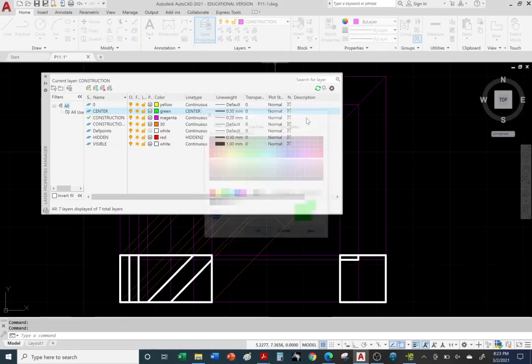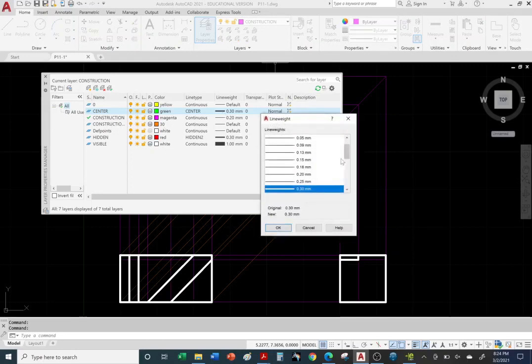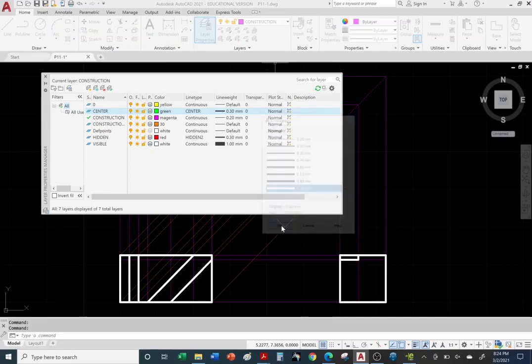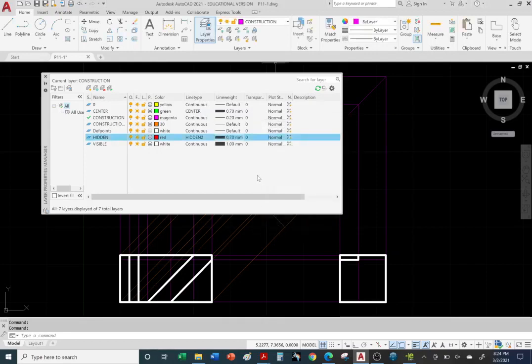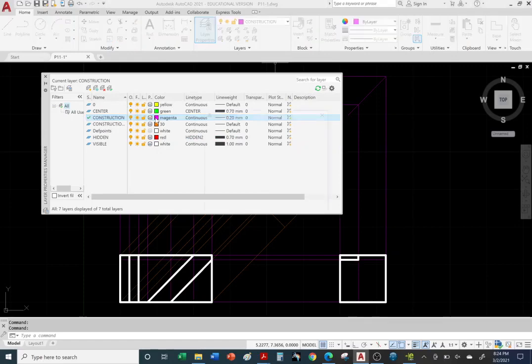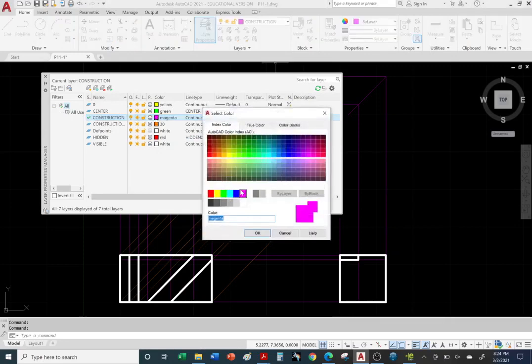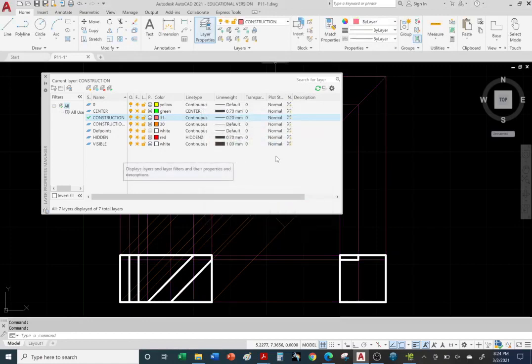And again, you want to follow the standards, and in your textbook it gives you what type of line weights to use. So we are following a standard, the American National Standards Institute and the American Society of Mechanical Engineers, the ASME standards. And we also have the international standards out of France. These groups of retired engineers and mechanical engineers come up with these standards for everybody to follow. They come up with the line weights, what type of title block to use, how to dimension, what type of threads to use, how to call out threads, etc. We'll talk more about standards later on.